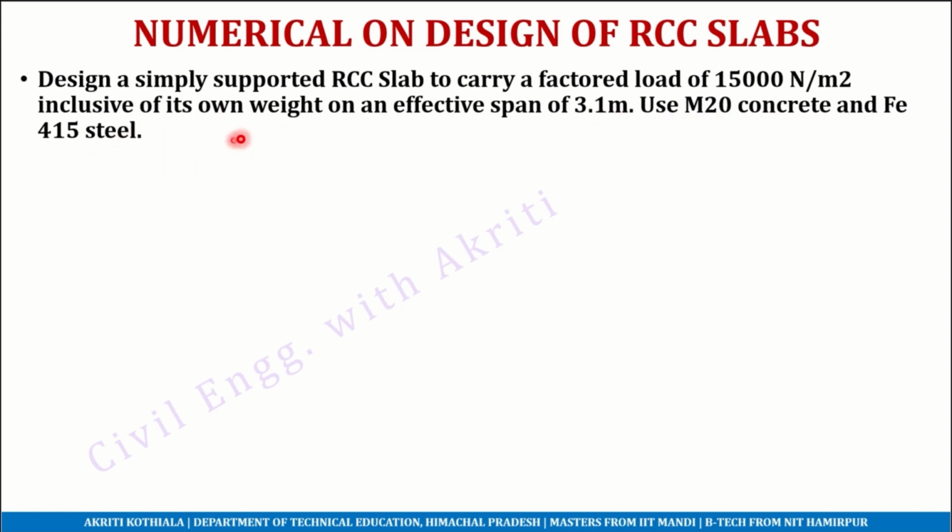So when we look at this question, first of all, we see that the word slab is not being supported by any prefix of one way or two way. So the examiner is not giving us the direct answer. We have to determine whether we have to design it as a one way slab or a two way slab. But like I told you, there is another keyword in this question, which is a simply supported slab. So a simply supported slab is always a one-way slab. So this is an indirect way of the examiner telling you that this is a one-way slab.